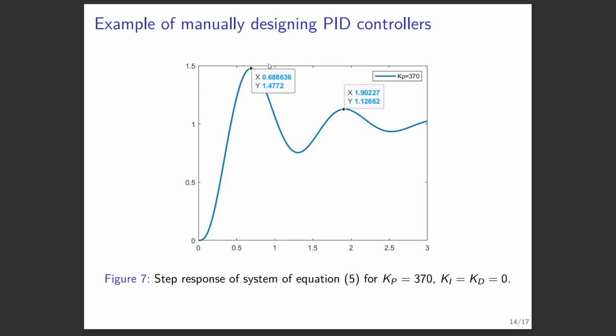So what I want is that in one period, the wave decays to a quarter of its value. You might say, wait a second, I have 1.26, and 1.26 is not a quarter of 1.47. No, it's not. But if you just look at the portion that is above 1, this is 0.47. A quarter, let's say of 48, is 12.